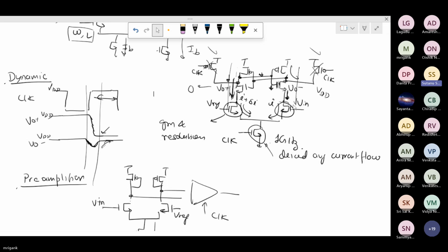Sir, it will work for a voltage greater than the drain voltage of the lower NMOS plus VTH. Yes, so basically this is not a saturation region current source. This is acting like a switch turning on and off. So mostly it will be the VGS. It will require at least some VGS drop, so it will be higher than VT. So if VT is 0.3 volts, then it will not work below 0.3 volt, or it will be working erroneously.